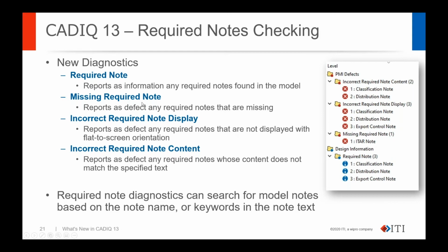There's another diagnostic called missing required note, and that's the one that would report as a defect any of the notes you're looking for that were not found. So in this case, the ITAR note was not found within the model, so that shows up as a defect: this model is missing its required ITAR note.